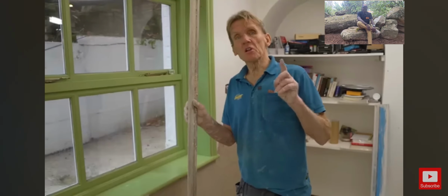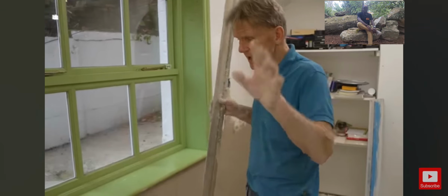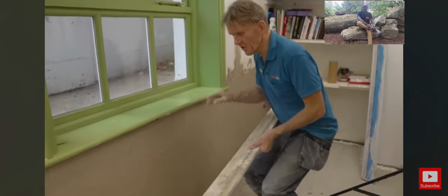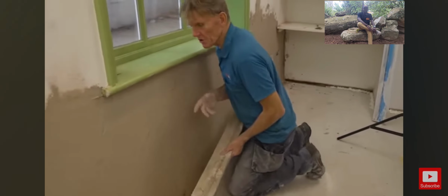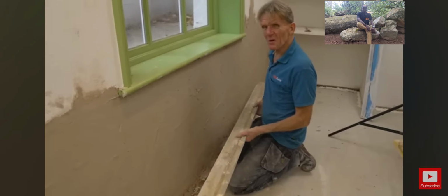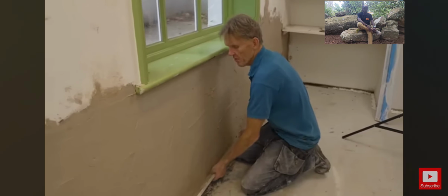Now this is something that I learned from Kirk Johnstone, who has an excellent YouTube channel on plastering. He gives you loads and loads of tips, and one thing that he told me is when you're putting this on, this is a little bit like monocouche, so let's pretend it's monocouche or whatever. The idea is put it on thicker than you need, put more on than you need, and then rule it off and just take off the high spots.